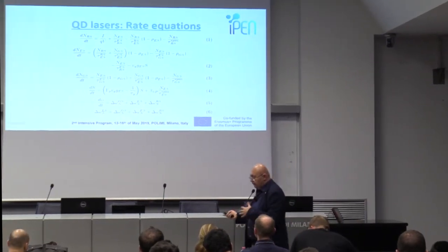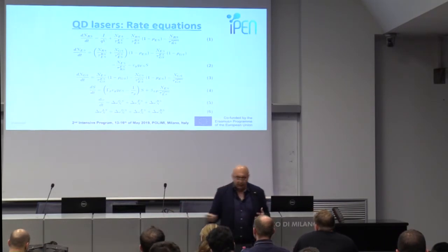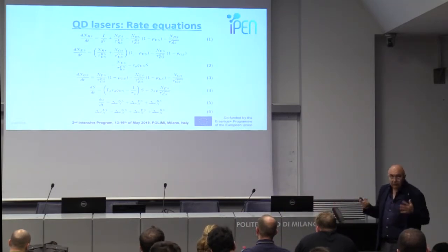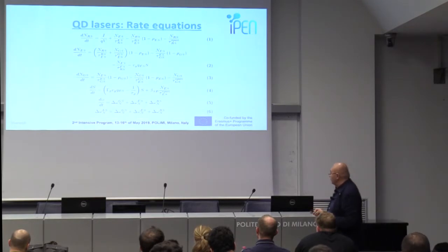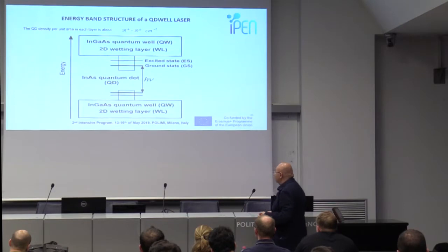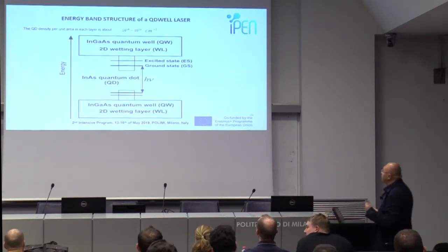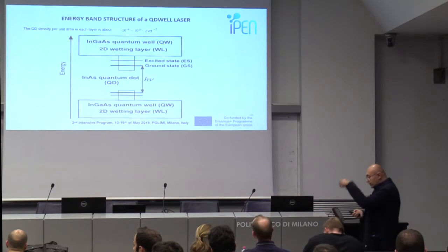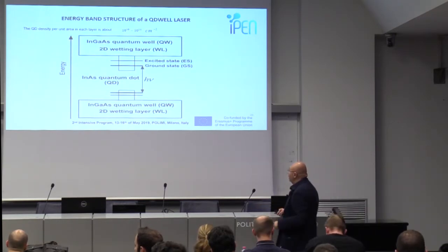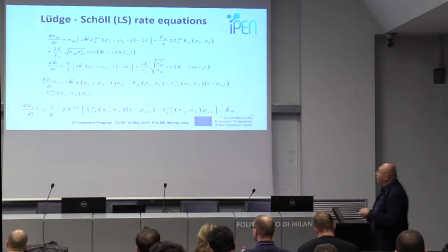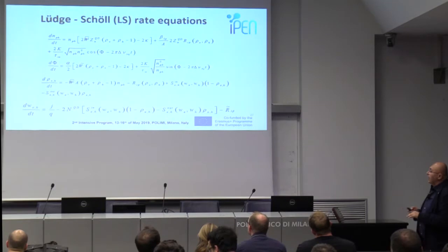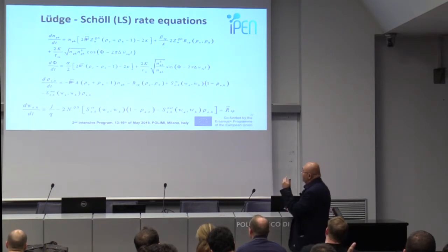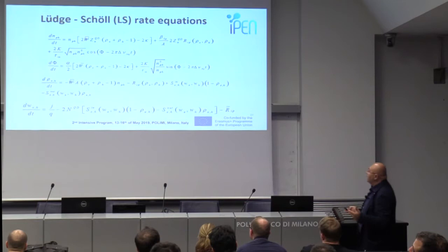The way to do it, you can use MATLAB, you can use COMSOL or other numerical tools, because the equations are strongly nonlinear. It is impossible to solve them analytically. There are other structures of the quantum dot lasers, the so-called quantum dot in well laser. Quantum dot is placed in the strained quantum well. In this case, the dynamic equations, the rate equations are very, very complex. You have to take into account the whole dynamics.